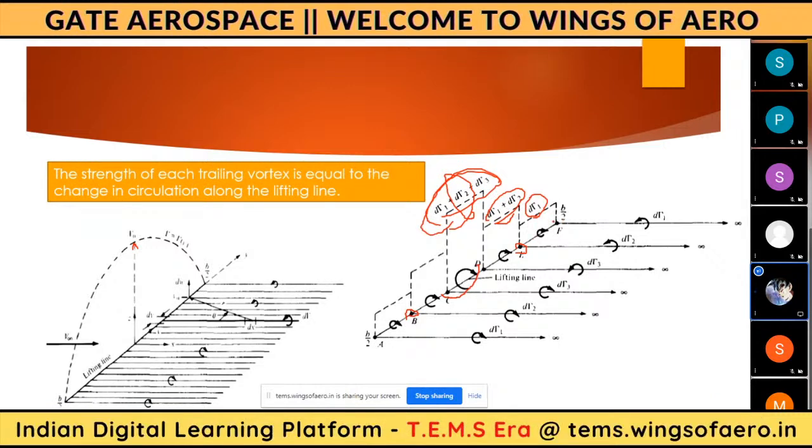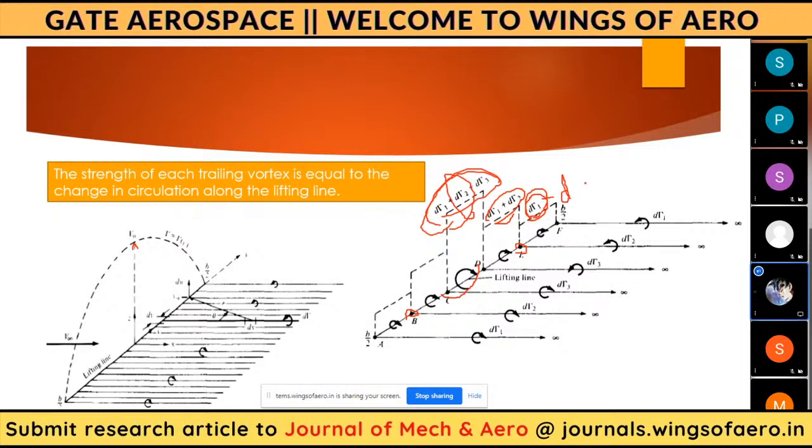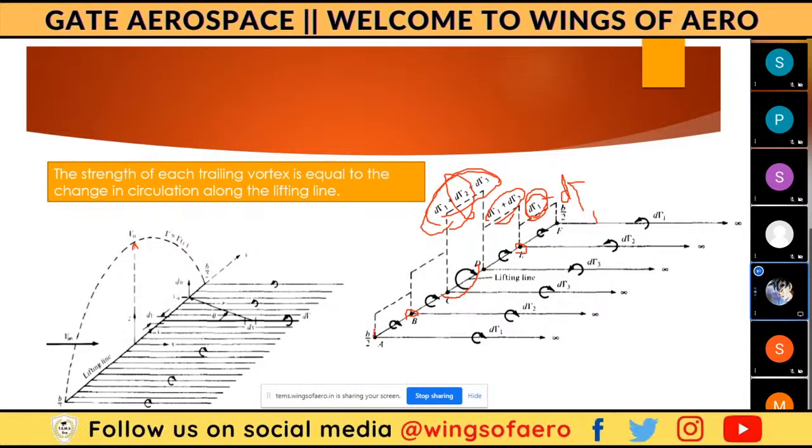But the last one near the tip only contributes from that single bound vortex only. That's why the strength of that bound vortex is d gamma 1. So altogether, while drawing the lift distribution curve, we will draw like this.